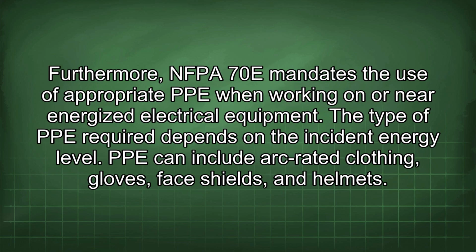Furthermore, NFPA 70E mandates the use of appropriate PPE when working on or near energized electrical equipment. The type of PPE required depends on the incident energy level. PPE can include arc-rated clothing, gloves, face shields, and helmets.